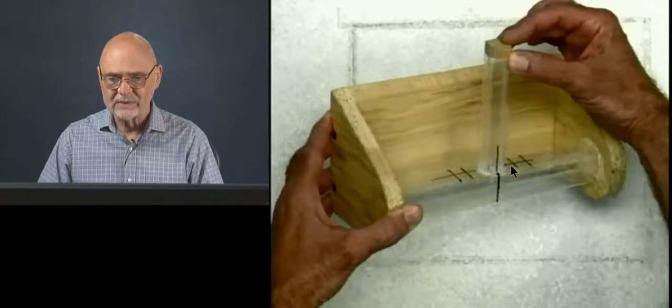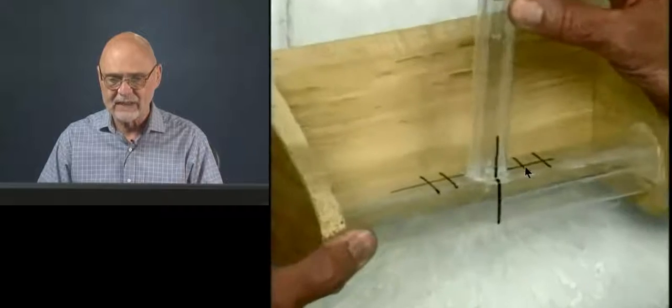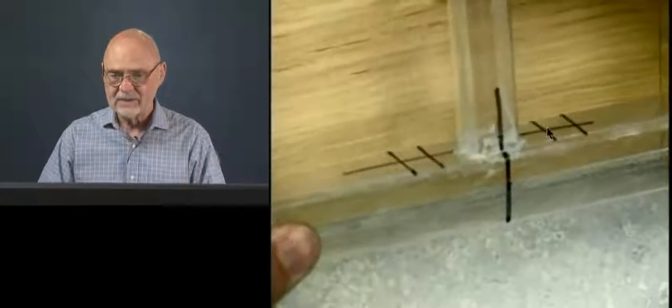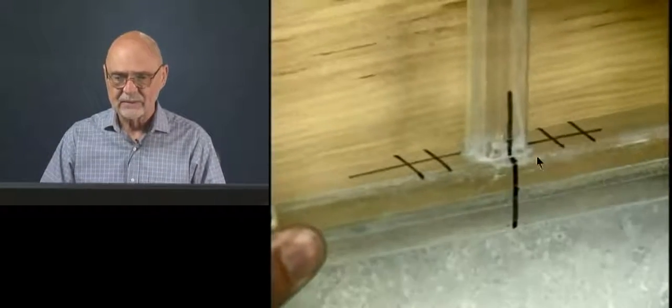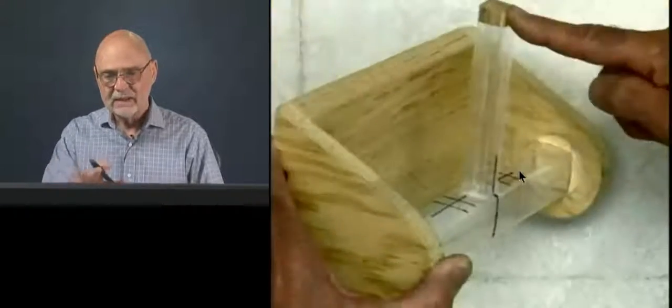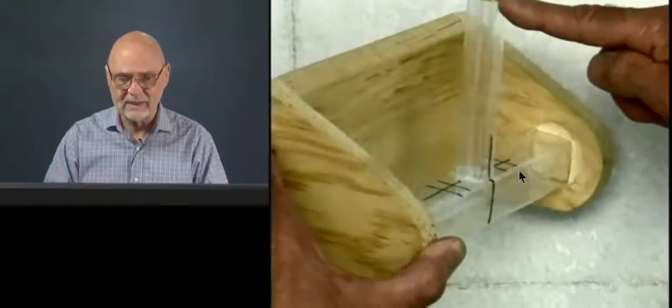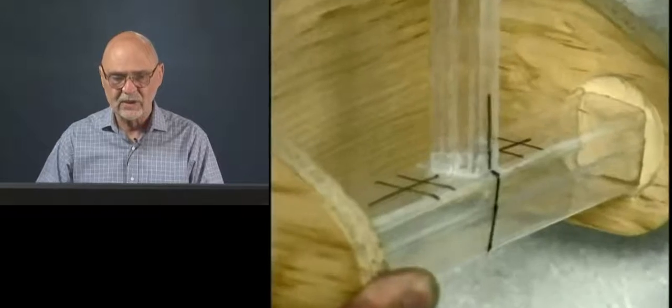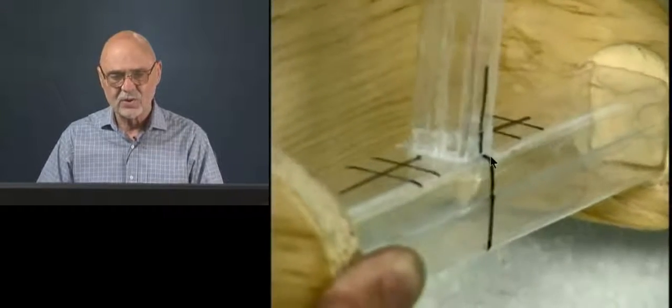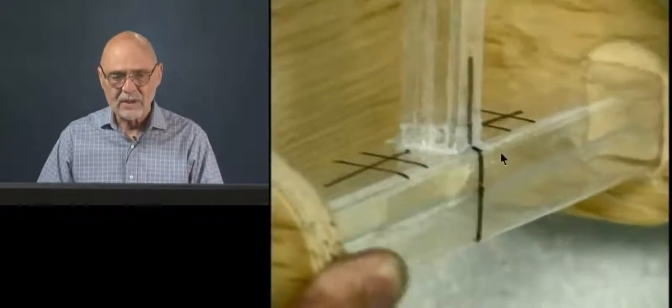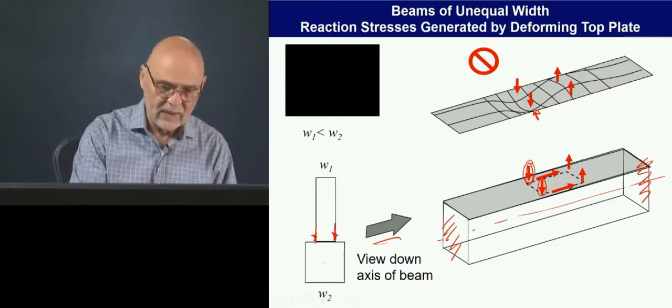Here you can see all the deformation that's occurring at that flat plate. That's this top portion of the rocker. So this is in-plane bending. Now this is a case of out-of-plane bending, so now we're loading it perpendicular. But again, you can see lots of distortion that's occurring, primarily because of this little offset that we have in this particular case.